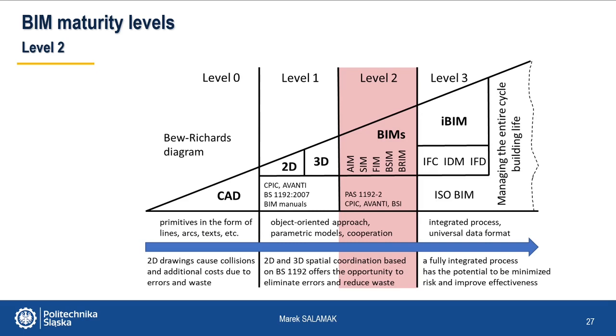The next phase, level 2, includes a managed 3D environment with attached data, but created in separate models by each design industry. These separate models can be combined together to form a related model, but they do not lose their identity or integrity. The data may include information on how the structure was assembled, that's BIM 4D, and on costs as well, that's 5D BIM.